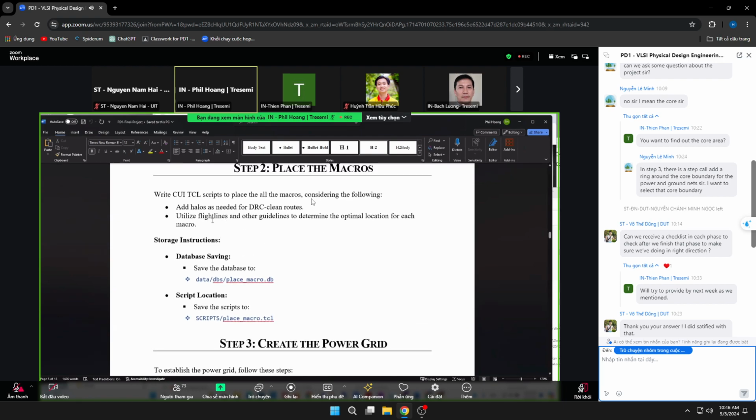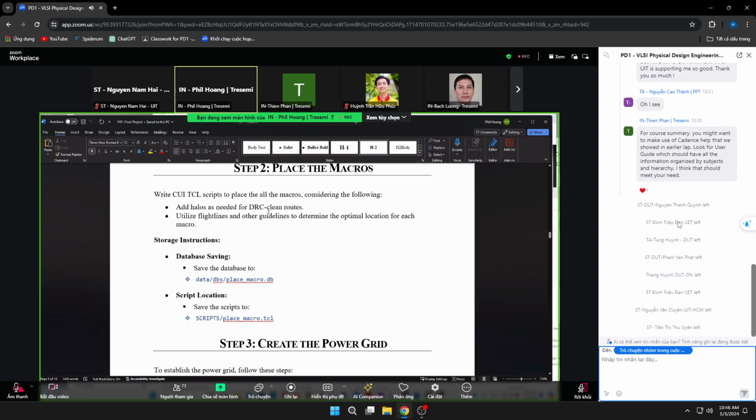So you do this and look at the labs, and then copy it and do it over here, and you can play with the placement of the macros. After you run through, you try one time and you see timing, and you might want to change the macro placement if you think it's better for timing. So that's your iteration. But try something first and then see what happens.